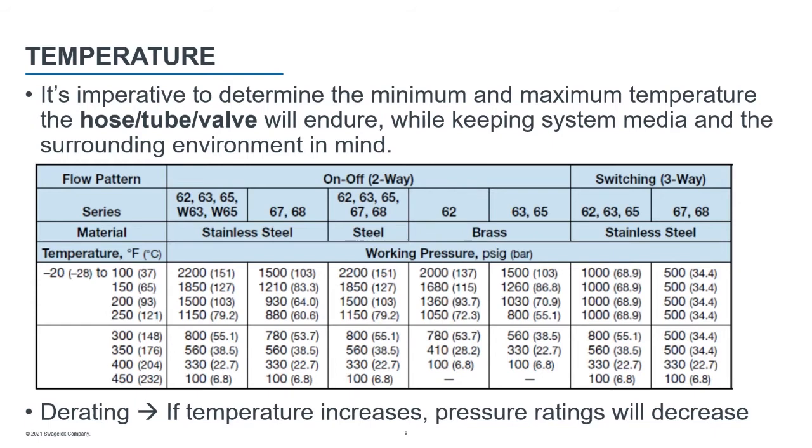In this specific case, elastomers in the valve can get softer at higher temperatures, so it won't hold as much pressure. And while we're on the topic of elastomers, one thing to keep in mind is that while softer materials can make better seals than rigid ones, rigid materials will be better at your high temps. So a soft material at high temperatures may be compromising your system. Therefore, our rigid materials are a great option for higher temperature applications.